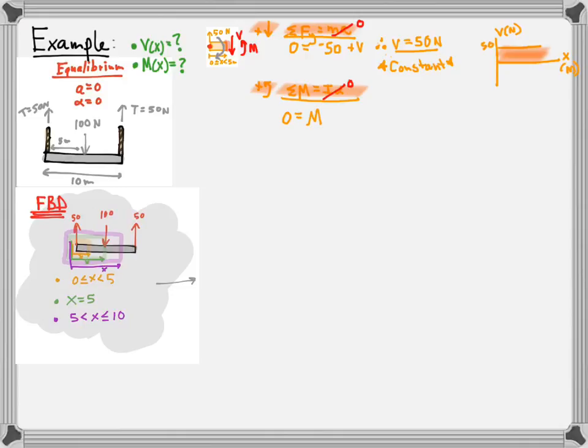And then we're also going to have that shear force downwards, and that's going to be some distance x, because we're trying to describe how it works at any distance between 0 and before 5 meters. Since that is a moment that would cause the bottom of this beam to be in compression, it's defined as a negative.